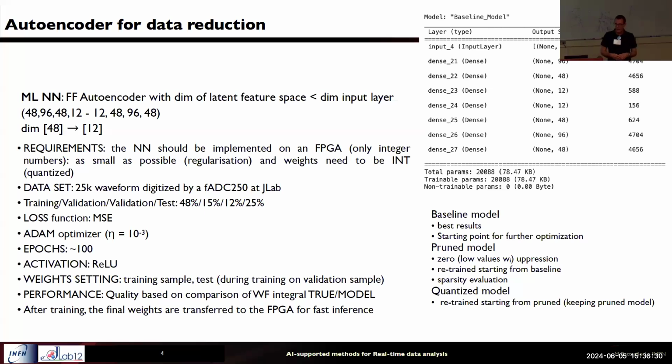An FPGA is not generic, or let's say it is specific hardware that works with integer numbers. While, as we discussed yesterday, weights are intrinsically real numbers, because usually they go from 0 to 1. It's just a matter of where you put your comma in the number. So you can imagine that transforming a real number into an integer is just reducing the number of bits that you use to code that number. So you do a kind of approximation. The approximation means that you are compacting your initial number into a smaller number, so you are losing part of this information.